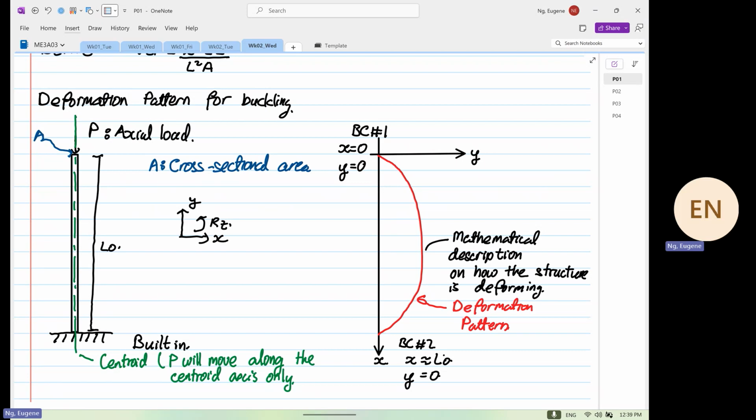Correct. Okay. How many of you drink Coca-Cola? How many of you have an empty Coca-Cola can now? I want you to try this. Stand on your Coca-Cola, and while standing on it, you press the center of the can, all of a sudden it will what? Correct. We are trying to predict the onset, before when you just touch the side of the Coca-Cola can lightly and the whole thing collapses.